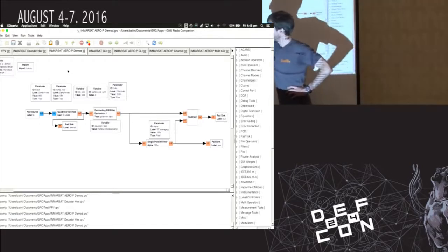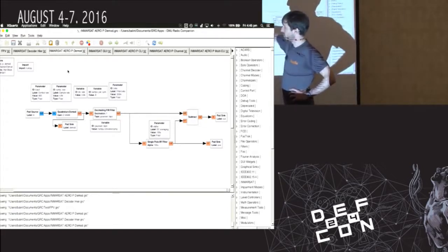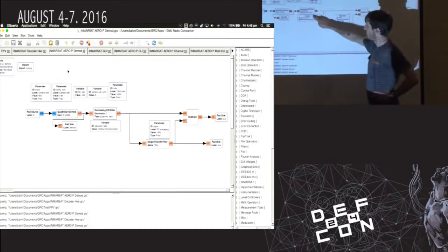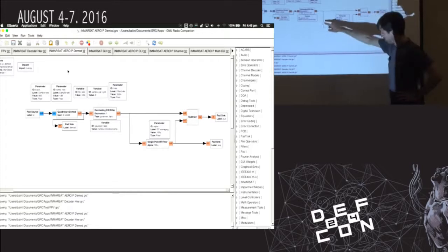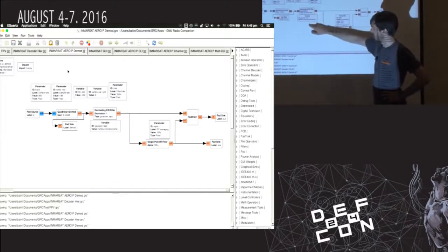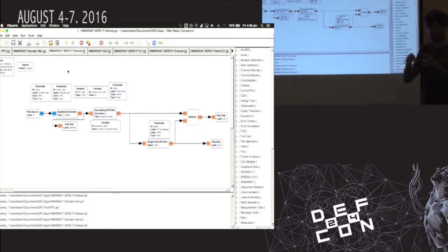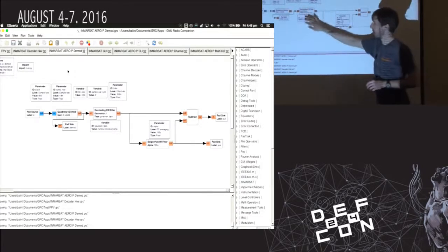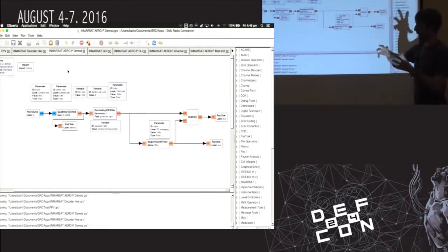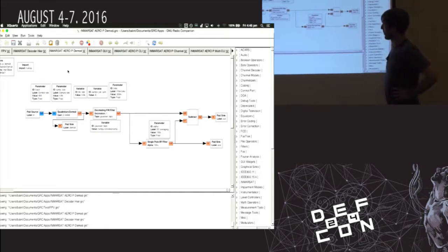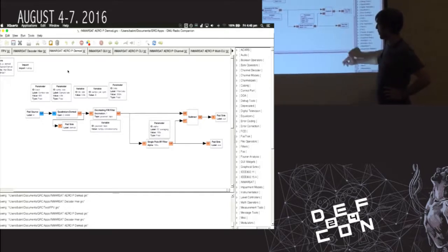So you have your baseband coming in to a quadrature demodulator, which is your FM demod. You go into an FIR filter. So I just made up some Gaussian pulse-shaped taps there. And what that does is you might have a really noisy incoming signal, and that smooths it out nicely so that you have some symbols that you can then do clock recovery on.